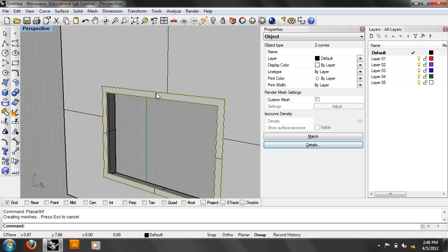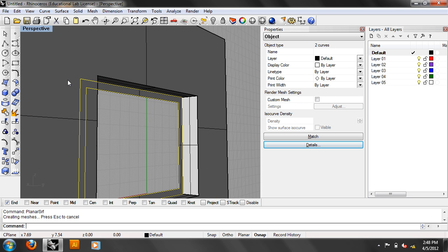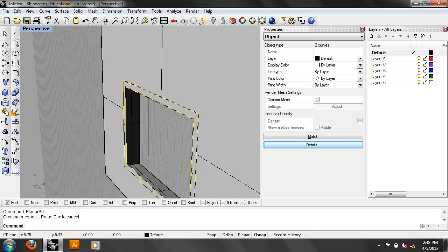I can get a surface with a hole in it. Now it's 2D. It's got no thickness to it at all, but I made a surface, okay? Extrude actually just makes a planar surface and then another planar surface at a certain distance, and then it makes all the surfaces in between that. So again, extrude is kind of like an automation as well. In the same way that Boolean automates this split and this trim and this join, extrude is actually automated too. It's a planar surface, okay?